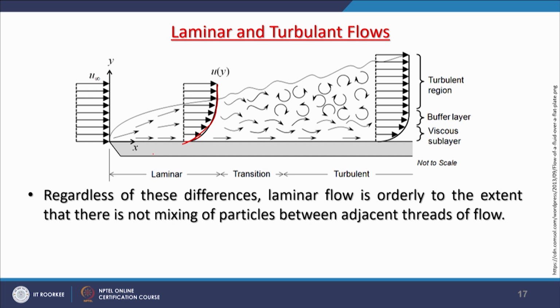All these arrows have been covered by this curve, and then turbulences are there, and later on these velocity changes between different layers may not be there except at the bottom, where friction by the bottom material is caused. So, what I am trying to say is, within a system, at some place the water may be laminar, at some place it can be turbulent, and at some place it can be laminar again. But converting a situation from turbulent to laminar will take time or distance. So, one has to be very careful or vigilant about this.